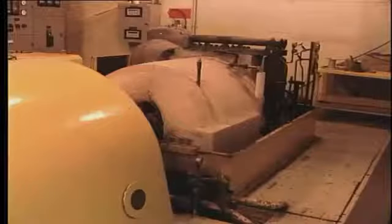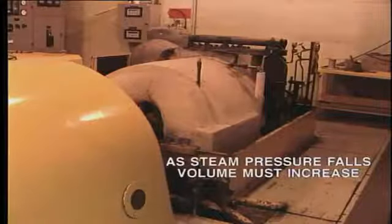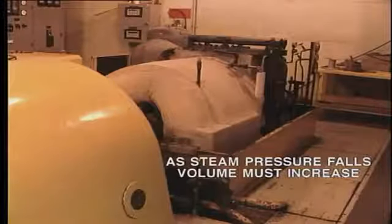This problem of specific volume is of concern to us when we consider the steam passing through the turbine. We know that the steam pressure falls, and consequently its volume must increase as it approaches the low pressure end.